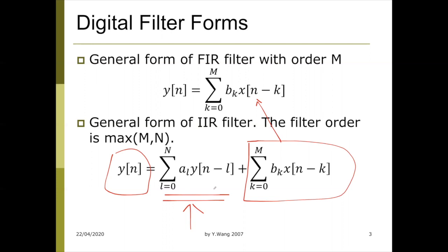Certainly, when we design an IIR filter, the algorithm will make sure the output fades out to zero. Otherwise, you will create positive feedback effects, just like when you set up any kind of PA system. Your microphone picks up the speaker, so it will get positive feedback even when you don't have any sound, because the sound will be amplified by itself.